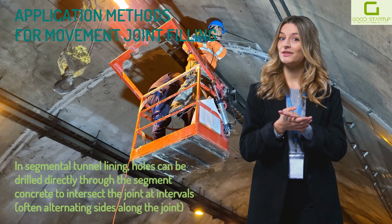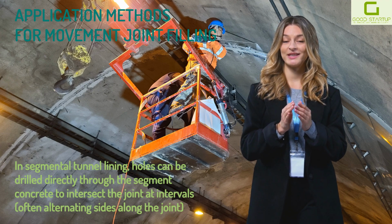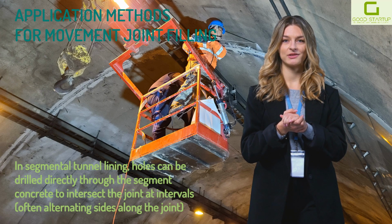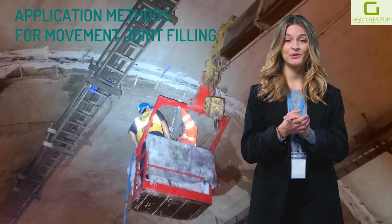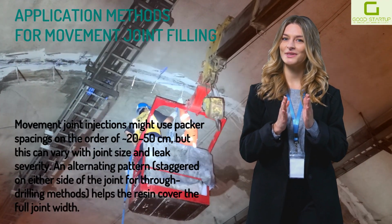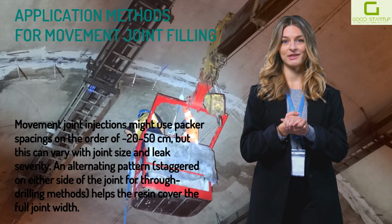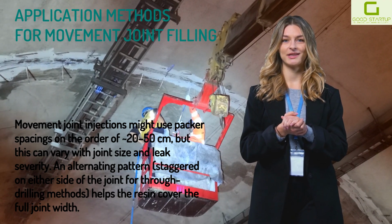In tunnel repairs, a specialized method involves drilling through the gasket with a thin injection needle, then injecting grout on the water side of the gasket. This targets the leak at its source and minimizes drilling through structural concrete. In all these techniques, the spacing of injection points is planned to ensure complete coverage. As a rule of thumb, movement joint injections might use packer spacings on the order of 20 to 50 cm, but this can vary with joint size and leak severity.